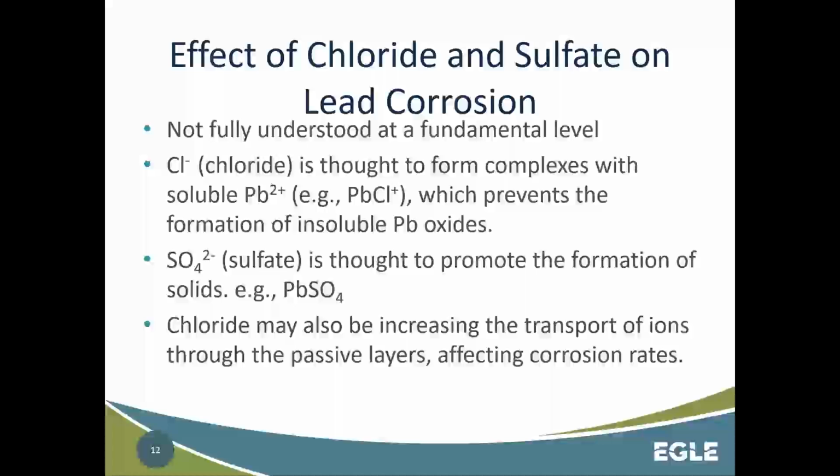Okay, so those chlorides are combining with the lead and staying soluble instead of going insoluble, oxidizing, and precipitating out of the water.